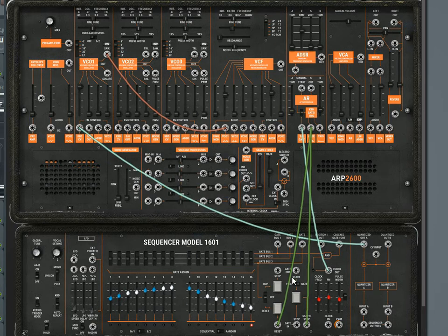We've seen one special use of gate bus 1 to modulate the speed of the clock. Now let's look at a special use of gate bus 2. If you look at this orange line here, gate bus 2, or gate bus 3, also controls the reset and the skip. What's this useful for? One very useful application is to produce sequences that are less than 8 or 16 notes. Right now this switch is set to off. Let us switch it to the reset. So now gate bus 3 is a reset signal.